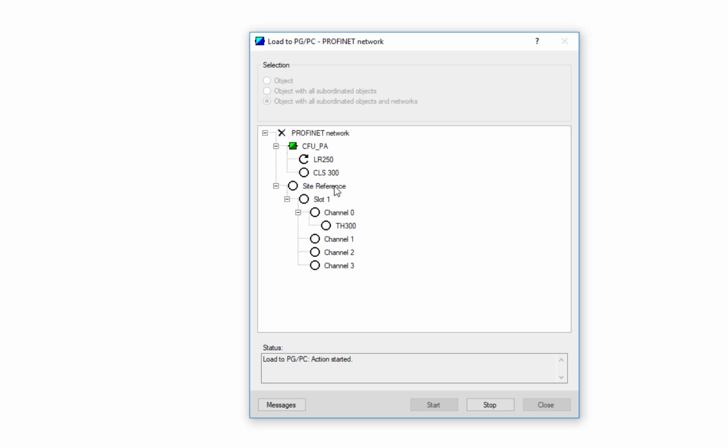As you start adding more and more devices, you're governed by the cycle time of the network and the acyclic gap that you get in that network. The more information you read back cyclically, the longer it takes to cycle round, and you only have that small gap to gather that information. Now, we're not governed by that on a Profinet network, so we get much faster update times.